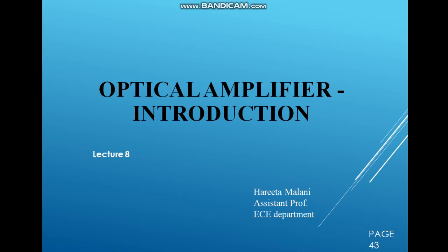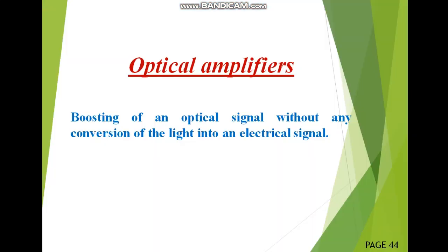So why are optical amplifiers required? The optical signals from the transmitters are attenuated by the optical fiber as they propagate through it. Other optical components such as masks and couplers also add loss. After some distance, the cumulative loss of signal strength causes the signal to become too weak to be detected. Hence, we need the signal strength to be restored. So, that's why optical amplifiers are required in optical fiber communication.